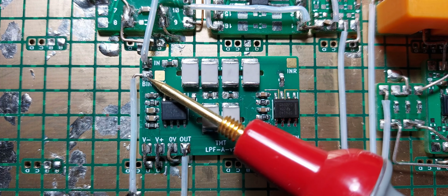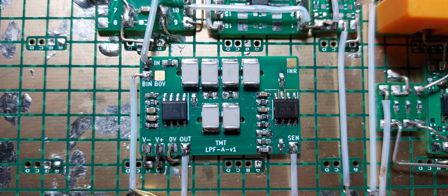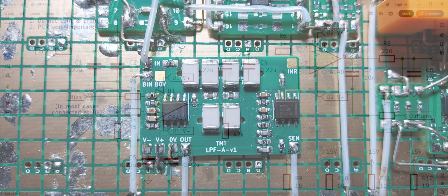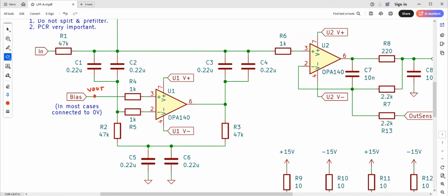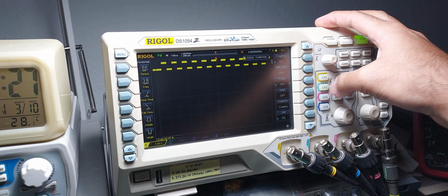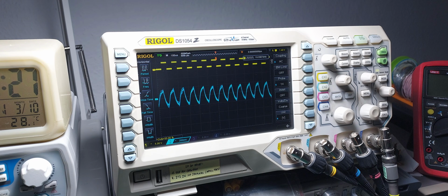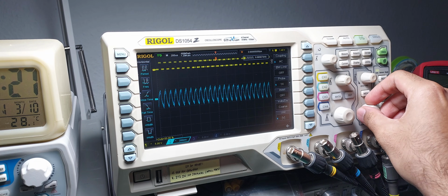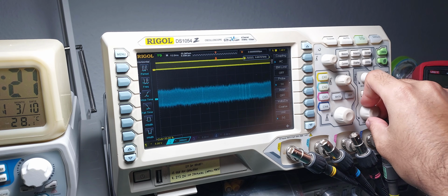The bias input is an interesting feature which sets the voltage at the lower end of the capacitors. If this is the same as the output voltage, the filter capacitors see no voltage across them, which might be helpful for reducing errors induced by dielectric absorption and leakage. The output ripple, now an order of magnitude smaller at 40 microvolts peak to peak, corresponds perfectly with the LTspice simulation.